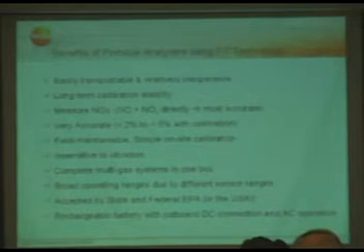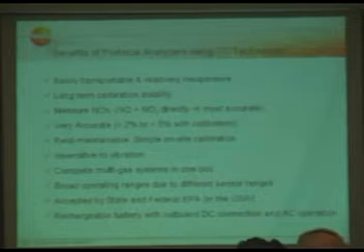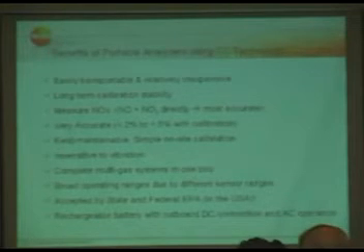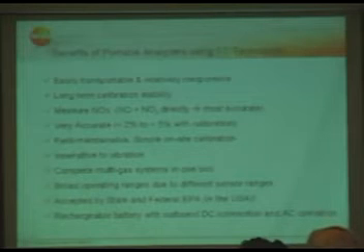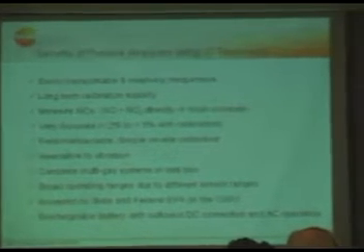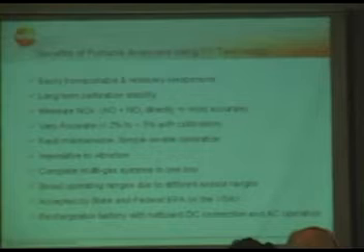Then broad operating ranges due to different sensor ranges. That means we provide a standard sensor for CO and NO, and we also provide a low concentration sensor for very low concentrations. This is a very big topic in Southern California in the US, because Southern California has very strict regulations regarding NOx, and all their gas engines, or especially low NOx gas turbines, within the next few years are not allowed to emit more than 5 to 8 ppm NOx.